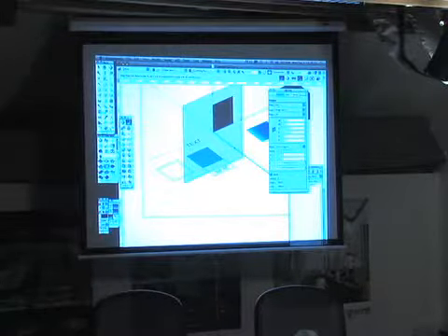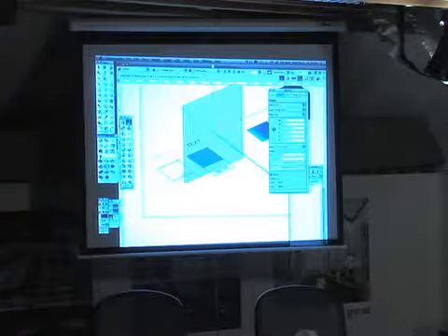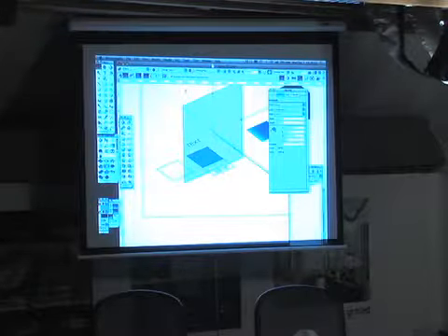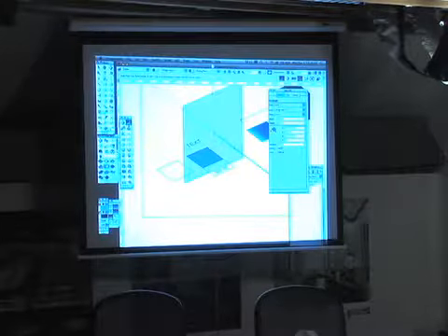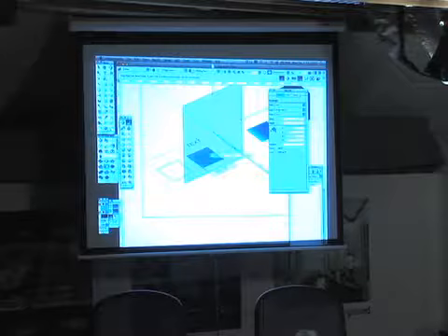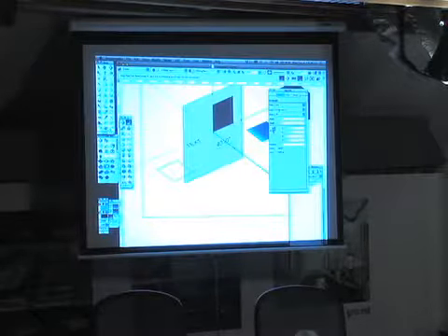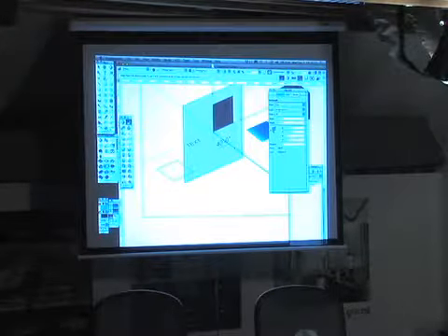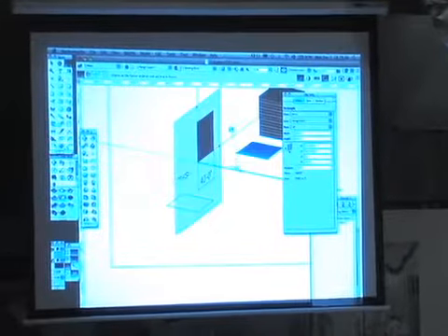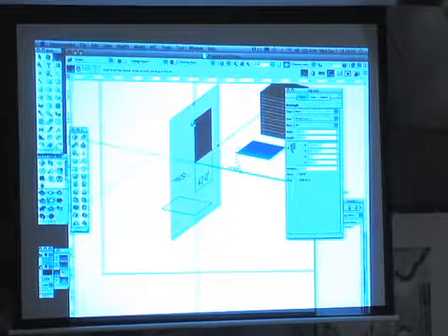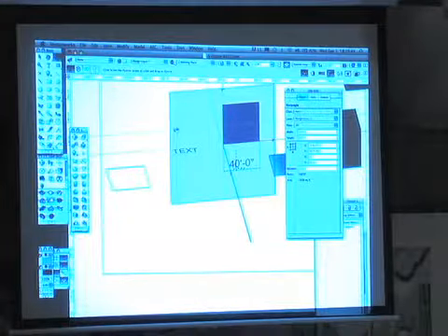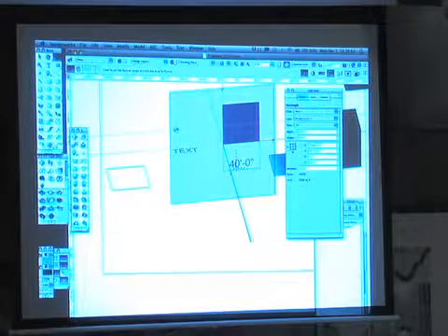So you click on align plane, you set your X and Y axis, you select an object. Oh, that's a line. It's not really going to do me much good. So select an object, align working plane, set my X, gives me a little X prime there down at the bottom, my Y prime, and that pops it up to my 3D working plane. So now everything stays true to that working plane, even though it is just a polygon object. It has no extrusion and has no thickness. It can show up and appear in 3D. So you don't have to really go into modeling as much as you used to be able to get some nice graphic presentations.